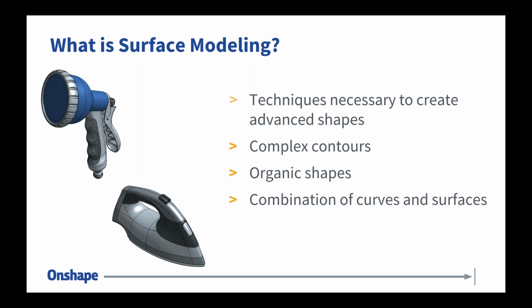Now, the key that I would stress with these kinds of shapes is they're a combination of first curves, then surfaces to create them. And the process of surface modeling is generally a bit different. Everybody kind of has their own approach to these kinds of things, but I think by and large, if you do a lot of surface modeling, a lot of times that kind of design work is done literally face by face. You're building faces of a model one at a time, maybe combinations at a time, but again, it's thought of on a face by face basis.